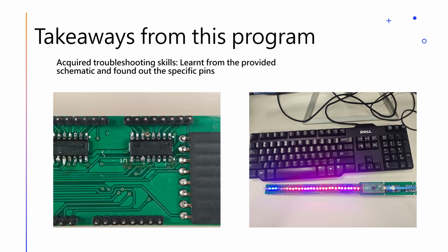Some useful troubleshooting skills I learned: from the provided schematic, I found out the specific pins and soldered again. Referring to the schematic, I identified several mistakes in the circuit design. I resoldered the components using tin, which helped me develop my troubleshooting skills. This experience taught me the importance of attention to detail and schematic problem solving in electronics.